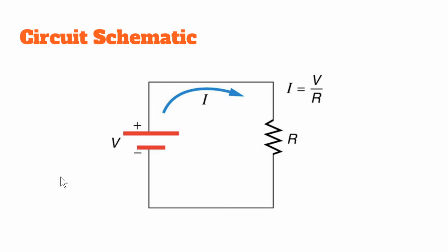One thing I do want to note is you never want to connect the positive to the negative without something in between. That's called a short circuit. You can actually damage your power supply. If it's a battery that has chemical energy, you could cause some kind of explosion, or some kind of catastrophic thing that you don't want to happen. So in general, a resistor is there to provide some resistance, something that'll stop the electrons from going so fast from point A to point B.